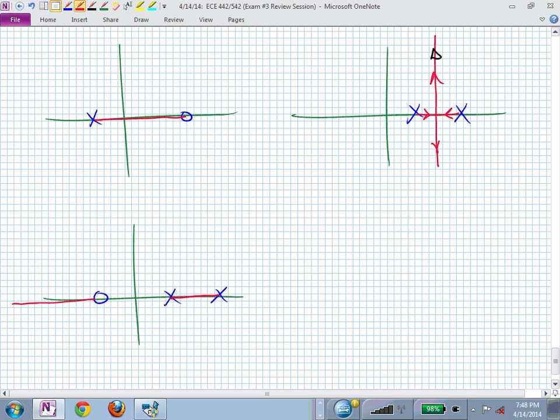How many root locus branches do I have? Where do they begin? On the poles. So I have 2 branches that are approaching each other. Do they meet in the middle? They meet between them, not necessarily exactly in the middle, because you have a zero. So you have to find the relative, what? Max or min?